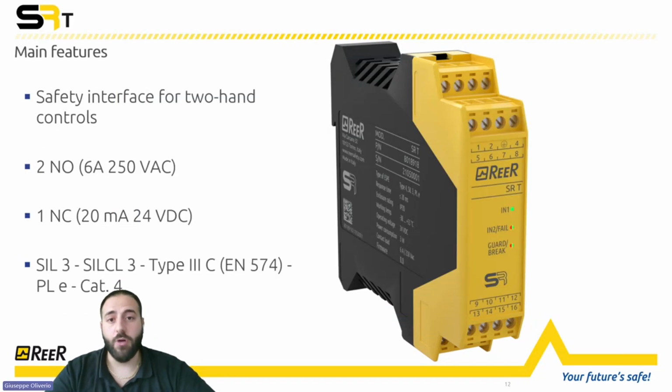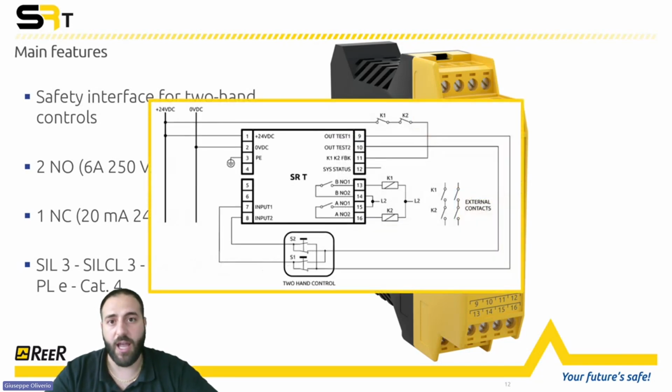In case of a two-hands control based on the EN574 type 3C, we can use the SRT, that is used for a two-hands control with switching contacts. And again, in this case, we have specific output tests with specific inputs, and then you can control the logic of a two-hands control. And the interface itself will check if you press both contacts at the same time. So it will check also the simultaneity of the contacts.